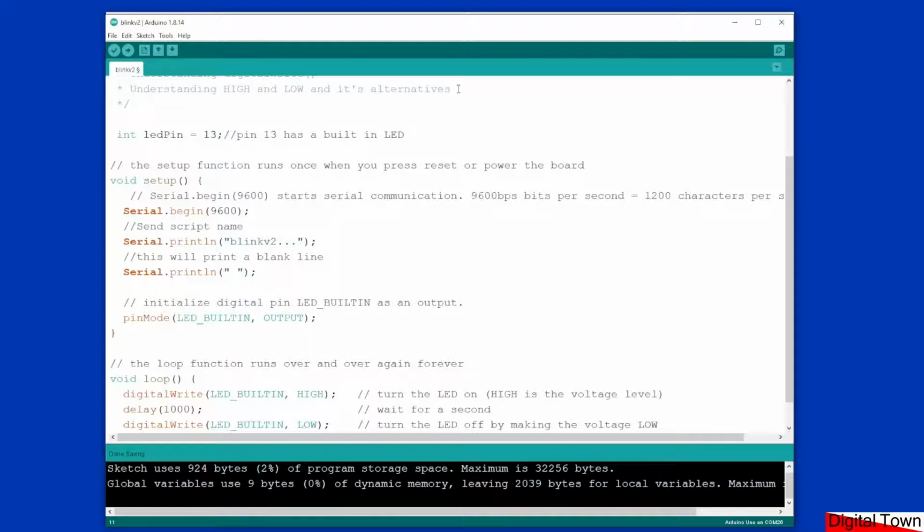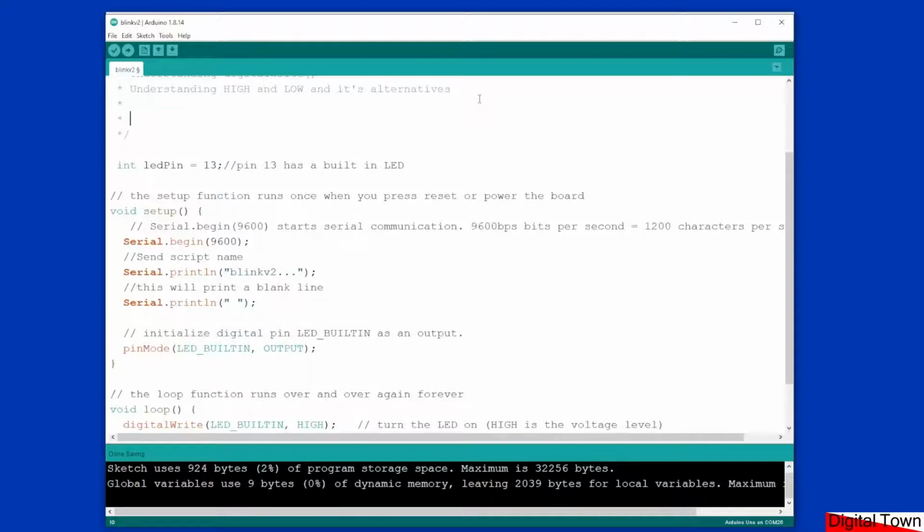What I'll often do is up here in the header, I'll write pin 13, LED. So if I was writing a motor driver, I know it needs 4 pins. I would write pin 8 to pin 12, motor drivers, just as a way of understanding how many pins have been used.